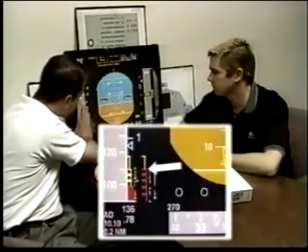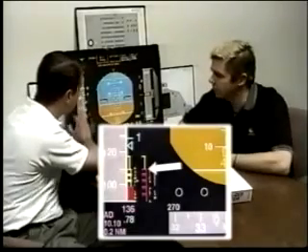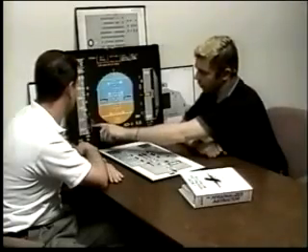Other times it's inhibited is anytime you're below 100 feet in the landing configuration, or on the 319 if you're in single engine and you have the flaps out of up. If we degrade from normal law, we still have VLS, but now we get a red and black bumblebee. Describe that to me. Okay, the top of that we call VSW. So V being a speed means V stall warning, although stall warning really can occur anywhere in here.